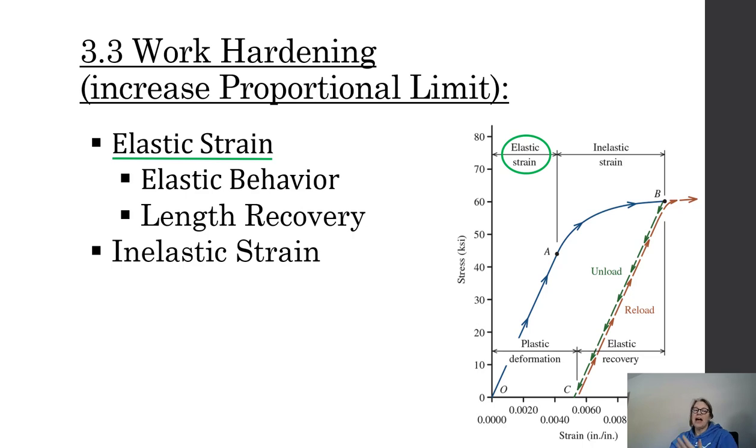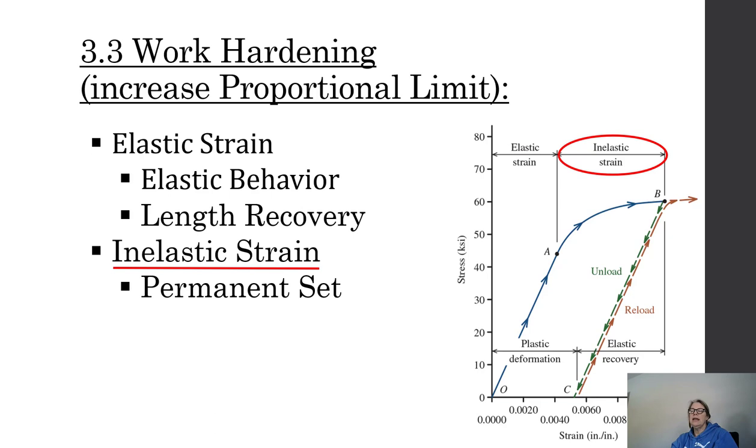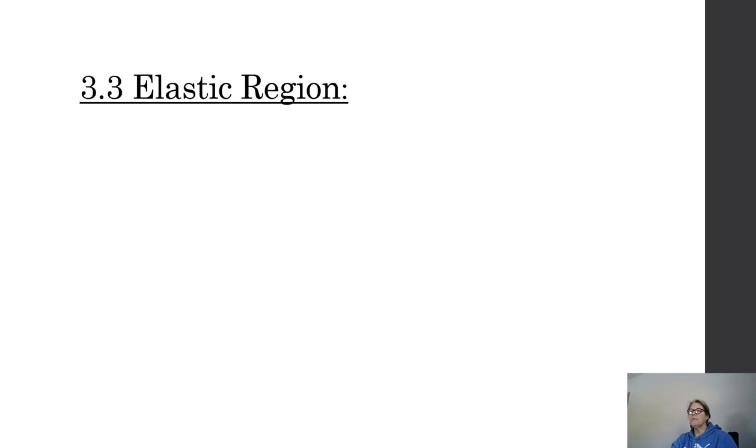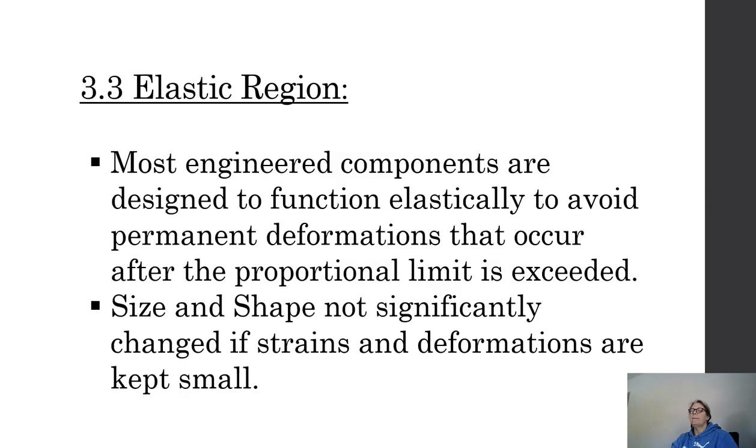Elastic means length recovery and cross-sectional recovery. It's just like new. When you move into that plastic, that inelastic strain, you have a permanent set. You have a permanent deformation, a permanent change in length. Most engineered components are designed to function elastically, because we want to avoid that permanent deformation, that permanent change in length.